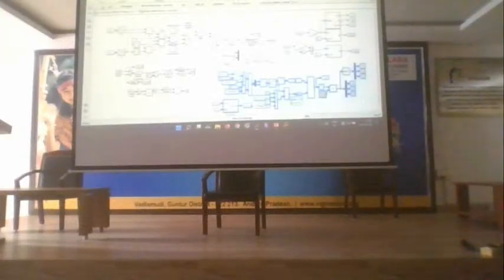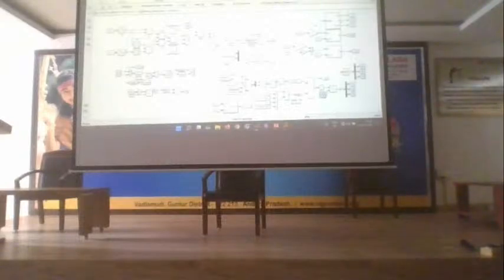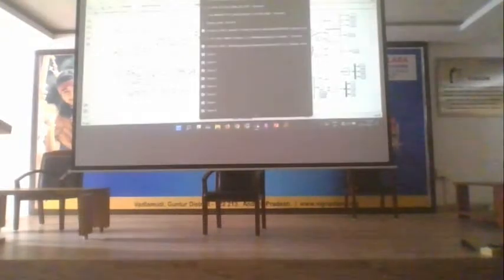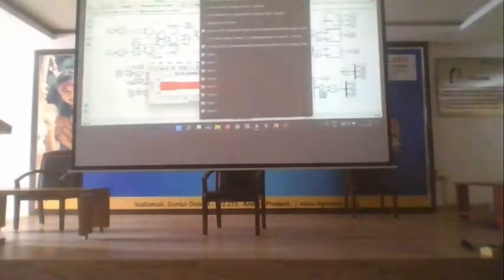Right? So what we need to do first of all, at the point of common coupling, is sense the voltage, and from that calculate the frequency, phase angle, and omega t. Then we convert into VD and VQ, and we are applying a DQ control strategy, which is better than the conventional control. Based upon our current reference power, this is ID and IQ, because I wanted to get a unity power factor. We can also see that it is operating at unity power factor.